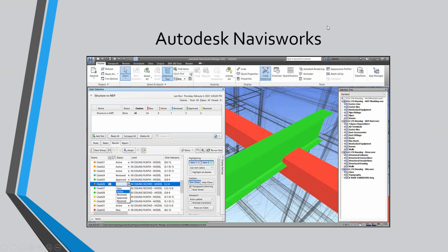And then in the image of Autodesk Navisworks, the clash detection software, you see that the person using the software puts the structural model and the MEP model together to see if there are any clashes. And it looks like here they discovered one. This is the green, looks like it's a structural beam. And then the red looks like it's an air duct of sorts. So when they run this, they see that there's a problem here. And of course, when this gets out in the field, they can't construct a structural beam going right through the air duct. So they'll have to coordinate, see who needs to move what.